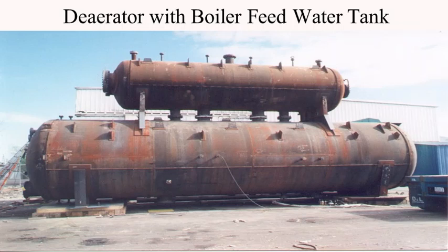This picture is of deaerator with boiler feed tank. Deaerator is always placed above the boiler feed tank. Inside the deaerator we have the arrangement for deaeration. So for that we have some trays and we have water spraying arrangement, and there is pegging arrangement too. That means pegging steam is provided from the bottom of the tray through which water is coming to the